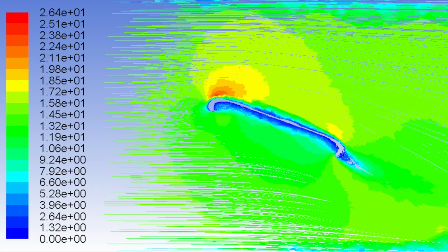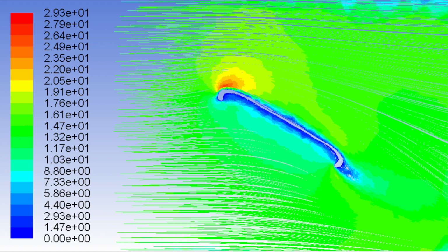Eventually, the angle of the disc reaches 20 degrees, which is replicated by the current ANSYS simulation. Looking at the figure, a strong drag force is created at the tail end of the disc, shown in dark blue, which means that the disc will continue to slow down. The deflected air creates a pocket of slow-moving air, which in turn leads to a greater lift. When the frisbee reaches its peak prior to its stalling, the frisbee attains the largest angle of attack.